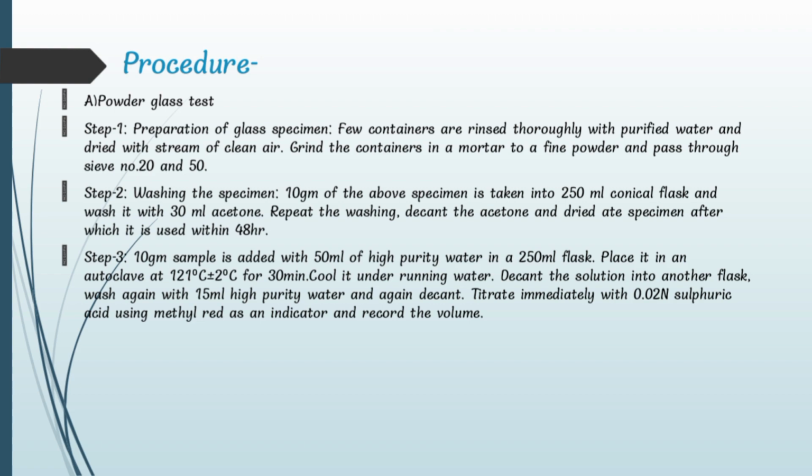Step 2. Wash the specimen. 10 gram of the above specimen is taken into a 250 ml conical flask and washed with 30 ml acetone. Repeat the washing, decant the acetone and dry the specimen, after which it is used within 48 hours.